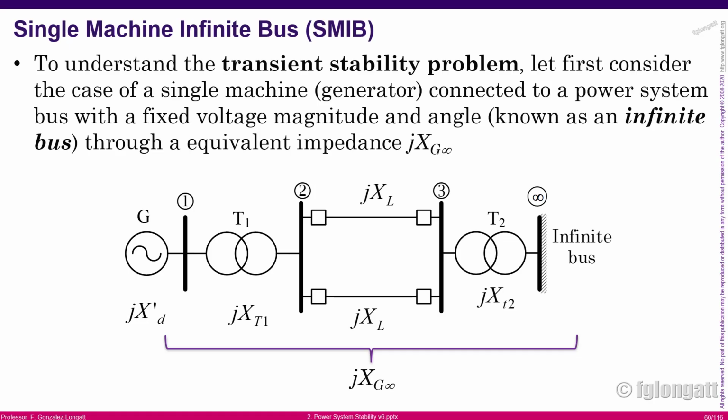Before I start, you must remember that I introduced the concept of infinity bus bar, okay? In the following discussion from here onwards, I will assume that the synchronous generator is connected to an infinity bus bar, okay? In this case, the infinity bus bar, you must remember, is a system that has a big inertia, and as a consequence, this voltage has constant magnitude and also constant angle.